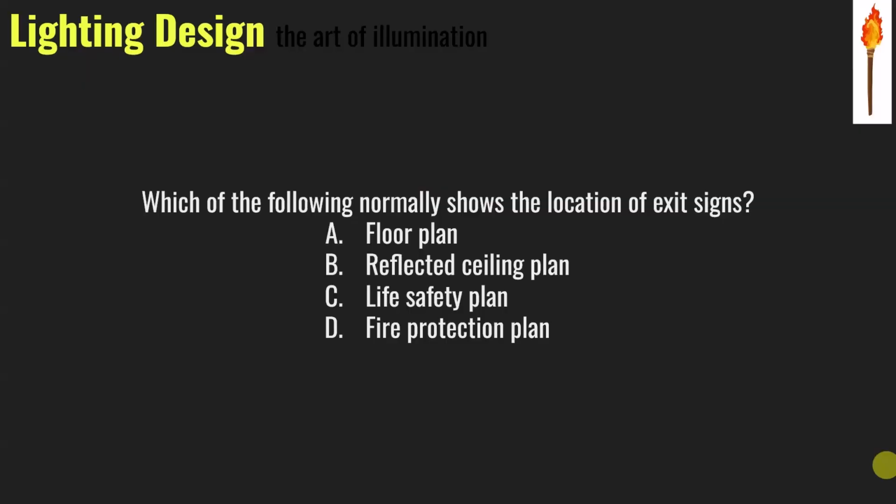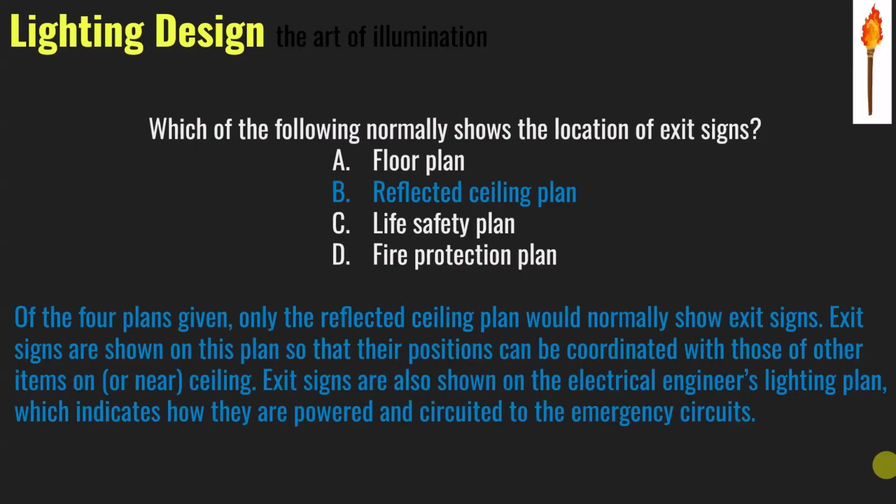Okay, exit signs, that's just nice to know that they would normally be on the reflected ceiling plan and that you would be a part of kind of that. The other thing that you would need to also be looking at is the mechanical plan overlaid with the electrical or the lighting plan or reflected ceiling plan, depending on how big the job is, to make sure that the mechanical fixtures are not in the same spots that you want lighting fixtures. Okay, if it's flexible ductwork, then they may be able to negotiate the mechanical into a different spot, but oftentimes it's the lighting fixtures that need to change or move.